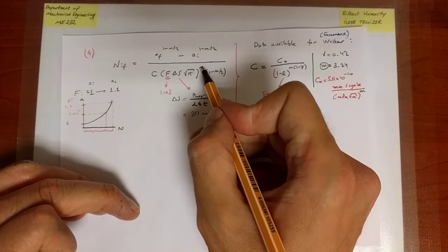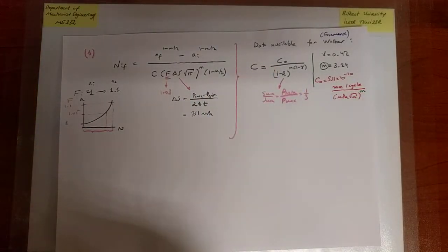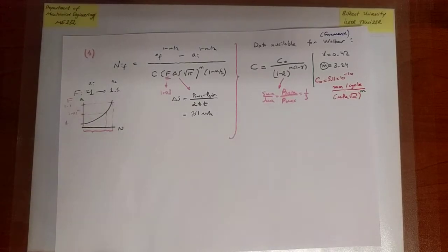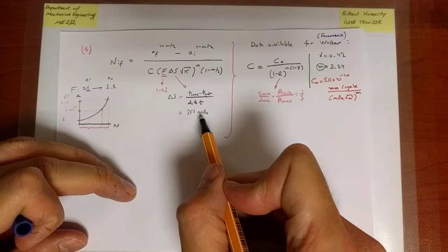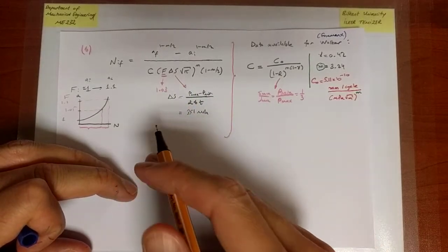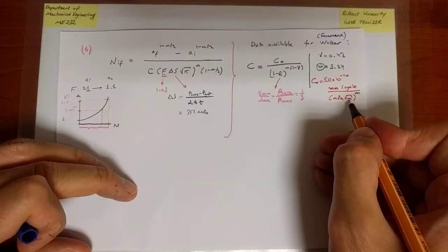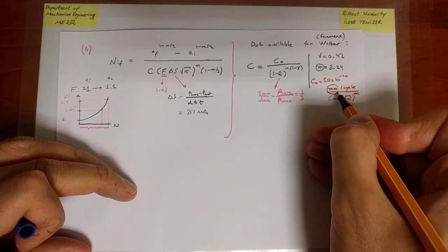Because there is an exponent m that appears here, that's where that m ultimately comes from. Okay, so the tricky point here is that the stress is in MPa. The usual units for stress intensity factor is MPa square root meters. But although everything is in meters, here I have millimeters.